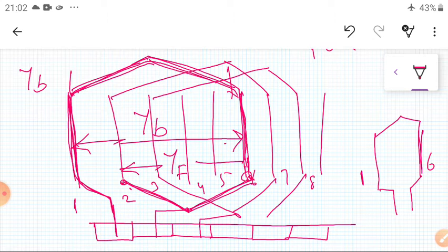Now after the front pitch, it is connected to the second slot. Once again it is connected to the back pitch and placed in the 7th slot. After that it comes to the next front pitch and is placed in the 3rd slot. So this is known as a back pitch, this is known as the front pitch. Okay, you already learned this in the theoretical part.